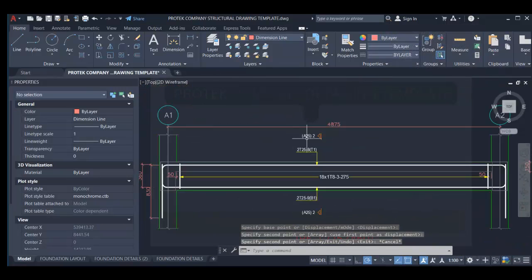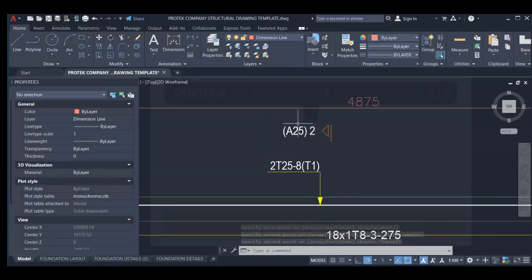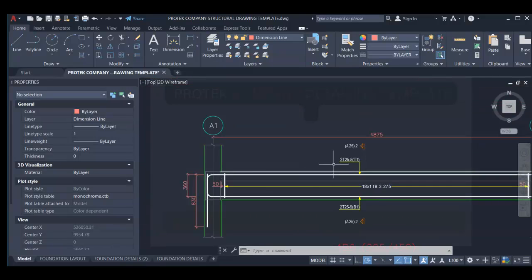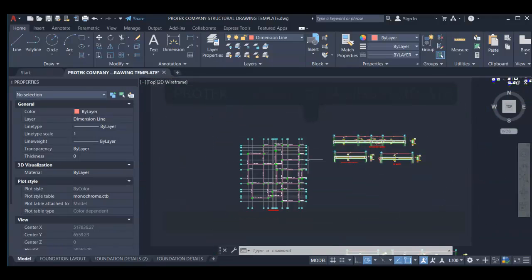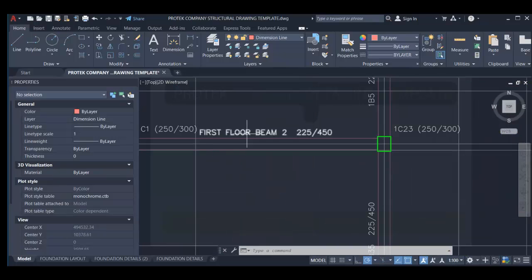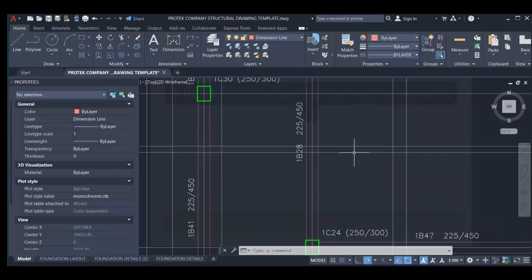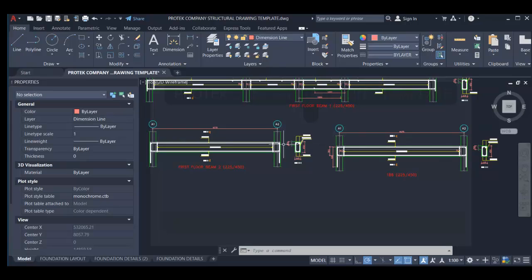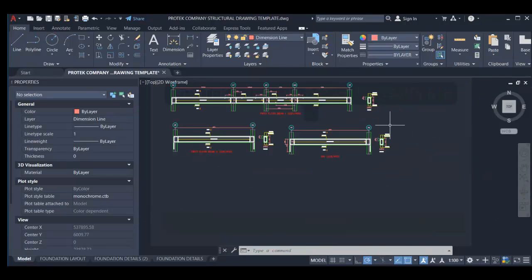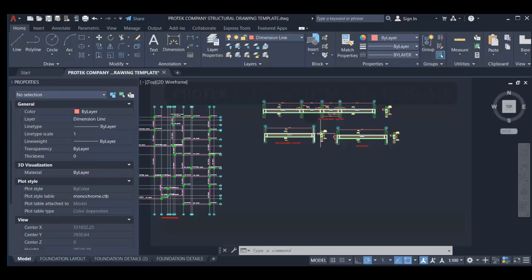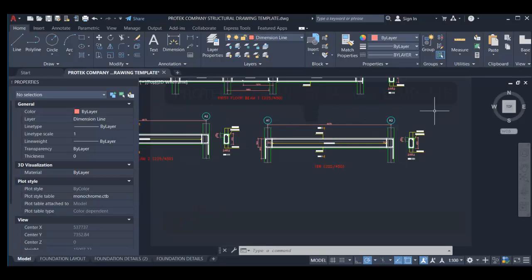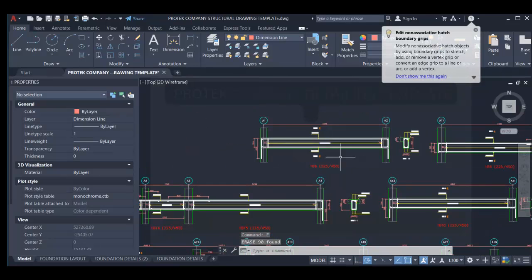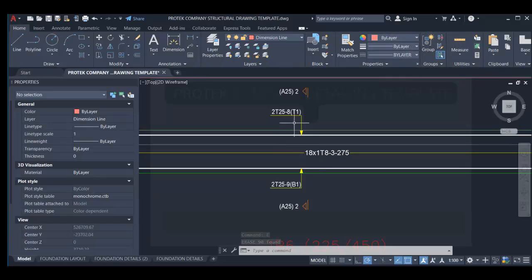After which you check the beam. This beam is on the same axis as this other one. So you can see the axis is A25. This other axis also is A25. So let's check the axis right there. We're having A25, which is this axis, and we have only this beam on the axis. But the beam repeated itself, and since it repeated itself, you have to delete it because we only copied it, we did not move it. Assuming we moved it, it wouldn't have been there. So we have to delete this because this beam is the same as this beam. E on the keyboard and get that deleted. You come over here, you will also notice that you only copied.